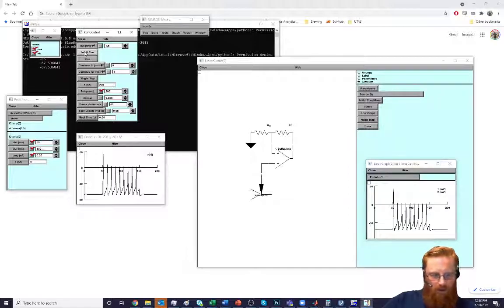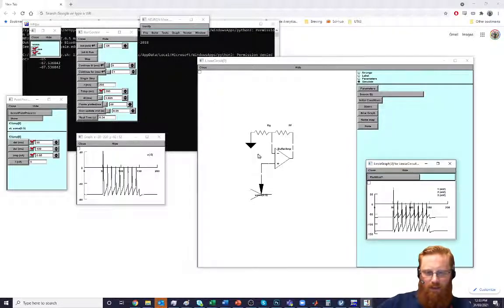Init and run. No, okay. I'm pretty confident this is going to work, but I'm starting to get nervous. Plot what? Let's do 3, which hopefully is going to be the voltage here. There we go. Right, view equals plot. So here is our 2 times amplified voltage. And the reason I'm doing this is because someone has been asking about pipette capacitance, right? So we can crudely simulate pipette capacitance, but it'll do for this demonstration.